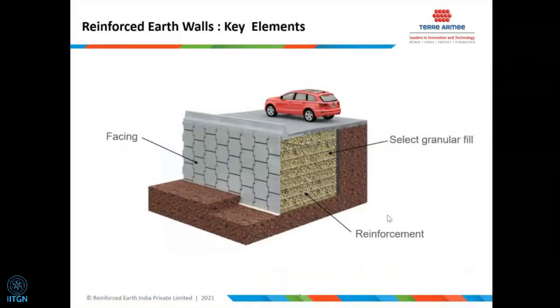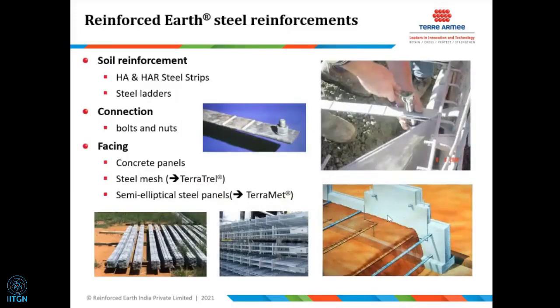That concept has been converted into the concept of a reinforced soil wall with reinforcement and with a facing element. The facing element is just a skin, and the entire soil mass reinforced with soil reinforcement acts as a gravity structure. So that's the basic background about reinforced soil. And we'll talk about the coherent gravity method. The coherent gravity method is applicable for inextensible reinforcement. As of date, steel is known as inextensible reinforcement.